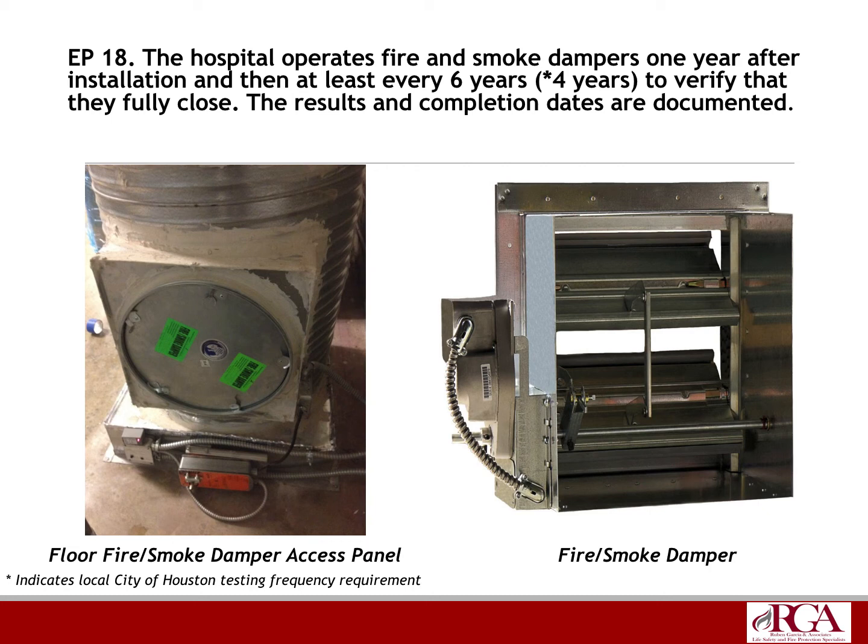Survey will come in and say, did you have any build outs? And you say, yeah, actually we had the shelf space built out. Did you add any fire dampers? Actually, we did. We added about 6 or 7 of them, from what I recall. He's going to ask you for that 1 year after installation inspection and testing. So you have to be savvy enough to know that you have to keep track of them. That's the challenge. And as you know, in healthcare, there's many challenges, and that's one of them.